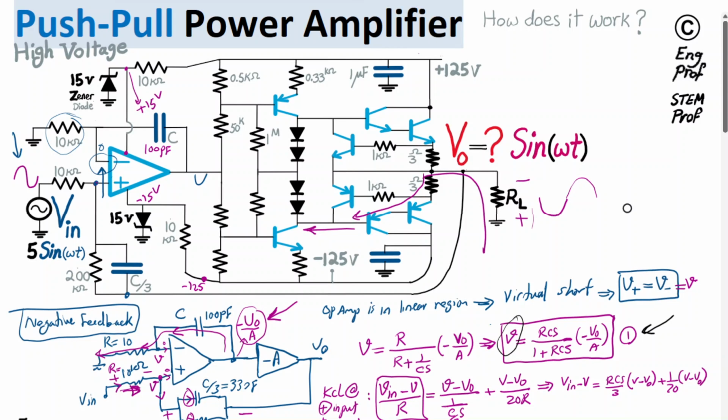For the output stage, let's say if this current limiting transistor is supposed to turn on, we want 1 milliamp to be able to flow through its collector. Let's make the assumption that this is a low current transistor with a current gain of 100. So when 1 milliamp goes through the collector, 1 milliamp divided by beta 100 means 10 microamp is going through its base.